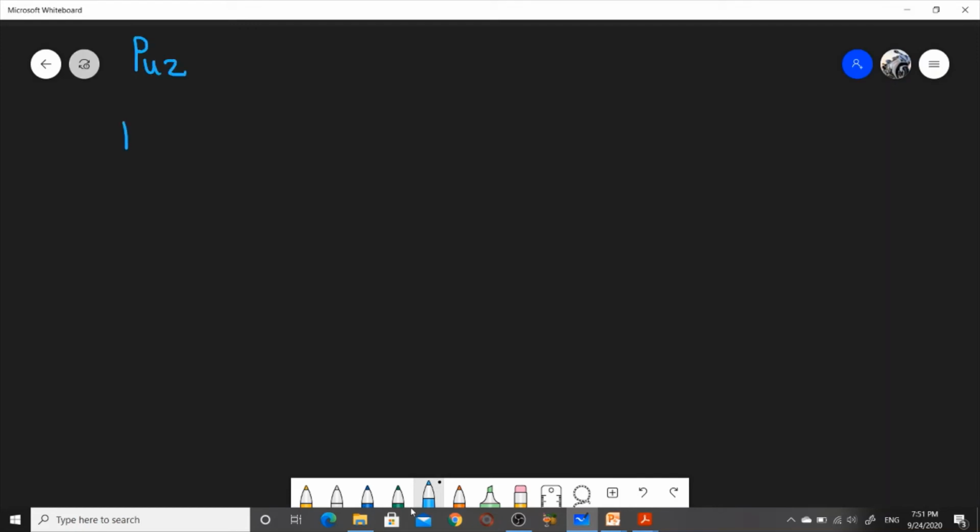So PUZ, we have an equation: 0.45 into FCK into AC plus 0.75 into FY into ASC.